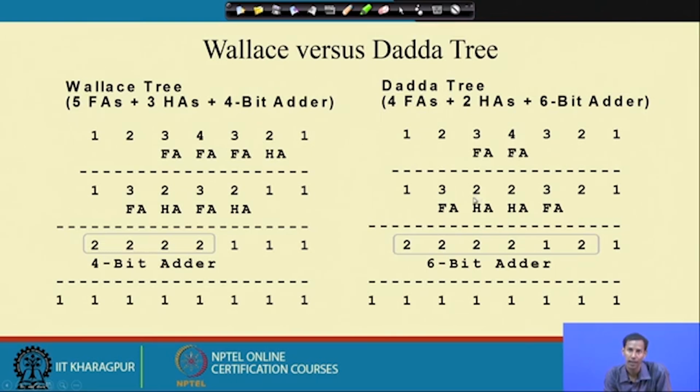So, that will produce 2. 2 produces 1, carry from the other level, 2, sorry. Then 3 is consumed and produces 1, carry from the previous level. So, that will produce 2. So, 1 here, the carry propagated from the previous stage, that becomes 2. So, now these 2, 2, 2, 2, 1 and 2, I need to use, and that will be using a 6-bit carry propagator. Now, I will get the corresponding results.